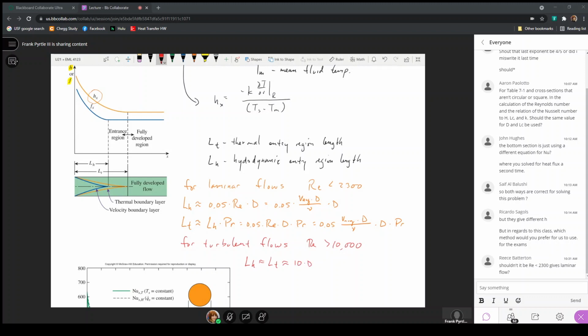So if we have a Reynolds number that is greater than 10,000, indicating it's what we call fully turbulent, because of all of the mixing that occurs between the molecules that make up the fluid, when it's a turbulent flow condition, because the fluid doesn't just move left to right through the tube, it actually moves through different radii, and the fluid is circulating a lot inside the pipe.